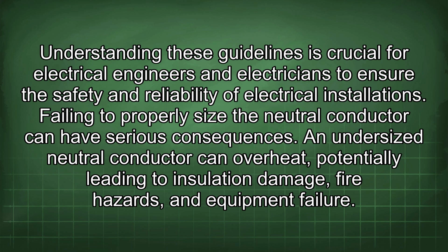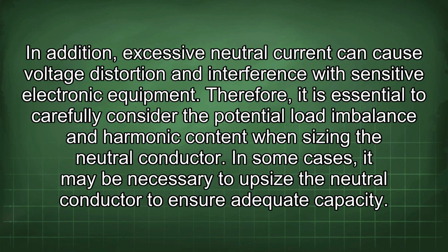An undersized neutral conductor can overheat, potentially leading to insulation damage, fire hazards, and equipment failure. In addition, excessive neutral current can cause voltage distortion and interference with sensitive electronic equipment. Therefore, it is essential to carefully consider the potential load imbalance and harmonic content when sizing the neutral conductor. In some cases, it may be necessary to upsize the neutral conductor to ensure adequate capacity.